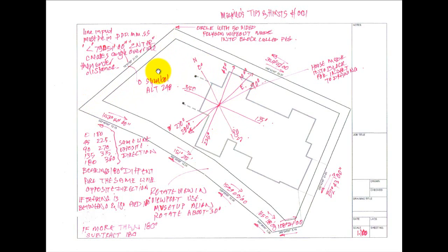So now it comes to putting them into AutoCAD. Just use a normal line function and go draw a line, click on the start point somewhere, and then before you go on you've got to override the angle. What you do is put in the less than symbol, and then what angle you want to put in.